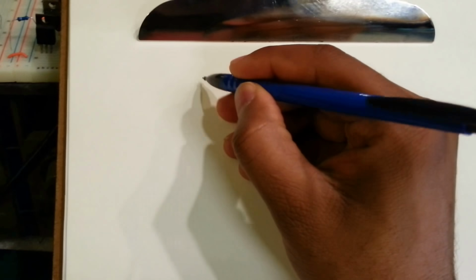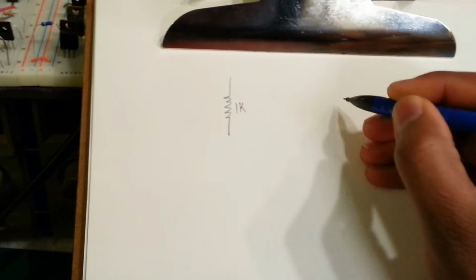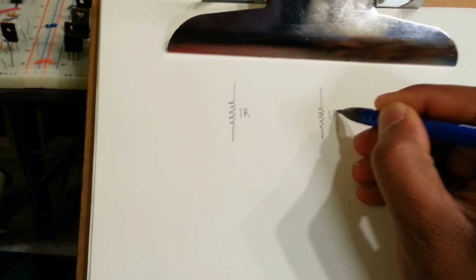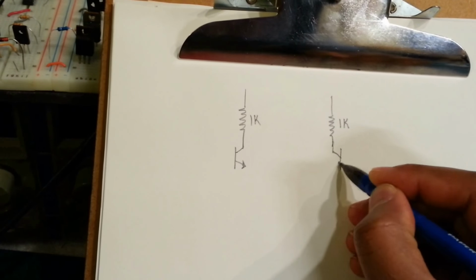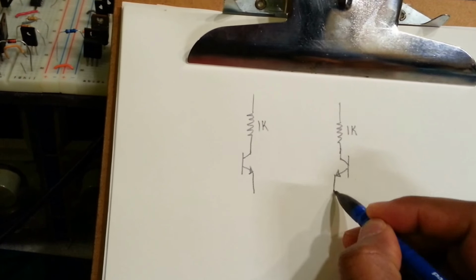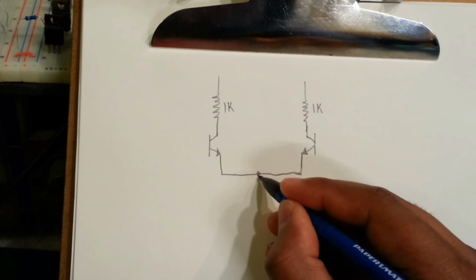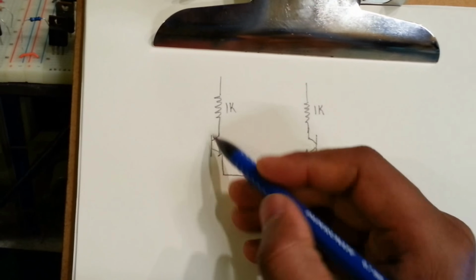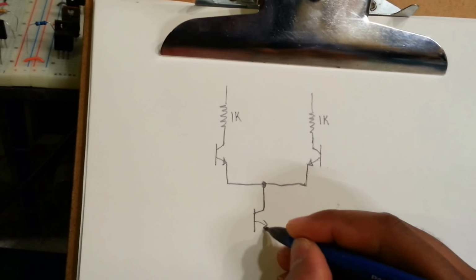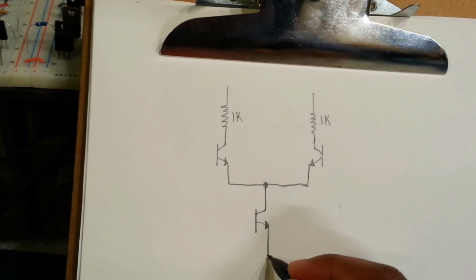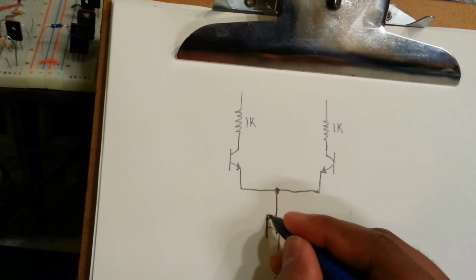So as told in the question, we're told this is 1K, the two collector resistors, and the two matched transistors that we're supposed to use for our differential amplifier, and no emitter resistor here for degeneration because it will be undegenerated, so that our gain will be directly proportional to the current that's flowing through these two transistors, and our current source to control the current, which will modify the gain of the amplifier.